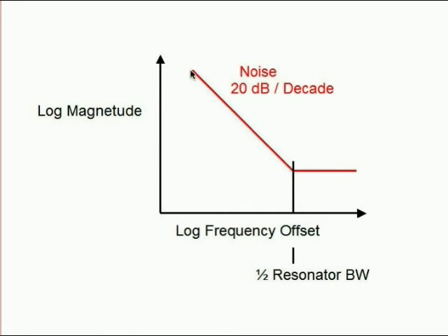Well, this of course seems rather strange if you think about it. We know with a practical oscillator that the amplitude is just stable, and what this is suggesting is that if we go down to very low offset frequencies, let's say a tenth of a hertz or a hundredth of a hertz, the amplitude is going all over the place.